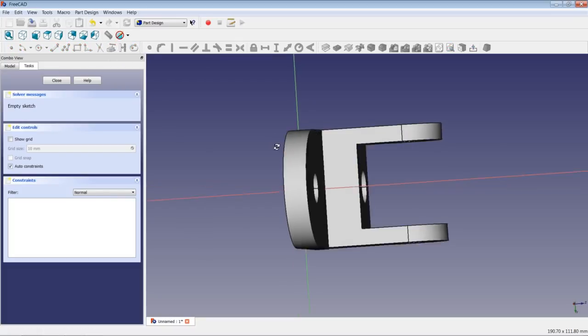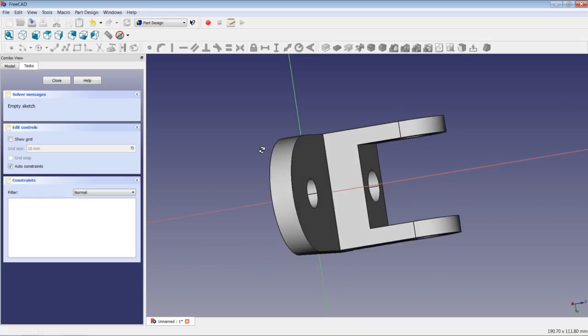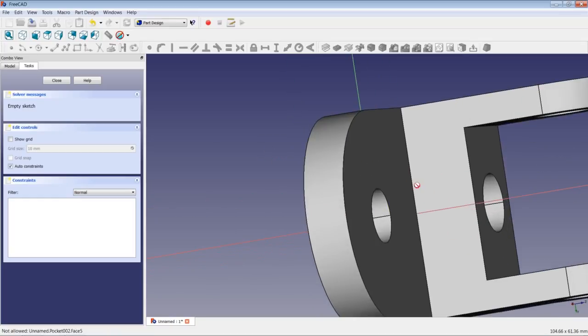So I click on the icon here, and as you can see now, if I move the icon over certain elements, it will highlight them so they can be taken from one geometry to this sketch I have now created. So if, for example, I choose this edge here, then I have the edge now as part of my sketch